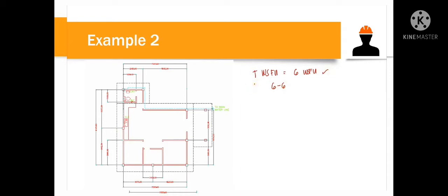We do not have a given value of our P, so let's use again 40 PSI, or that is equivalent to 275.8 kilopascal. And then, this is only one story, so our static pressure is equivalent to 0. It is a one-story building only.